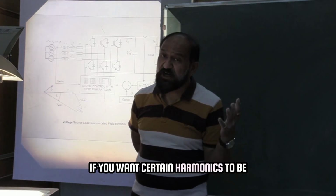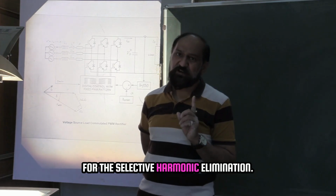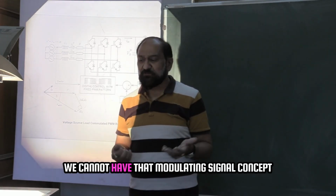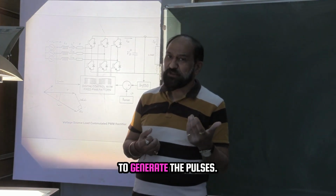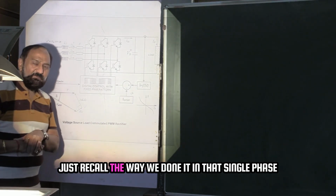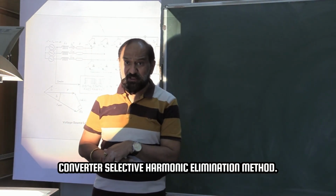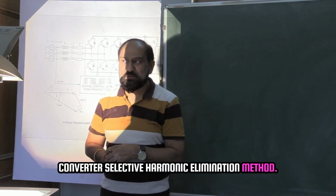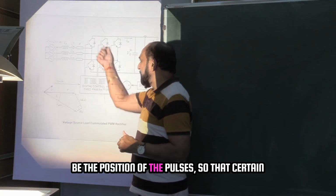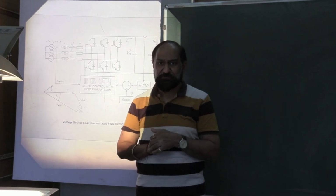If you want certain harmonics to be absent all throughout, we have to go for selective harmonic elimination. But with selective harmonic elimination, we cannot use the modulating signal concept to generate the pulses. Just recall the way we did it in the single phase converter, the selective harmonic elimination method. We can use that method to find out what the position of the pulses should be so that certain harmonics are completely absent all throughout.